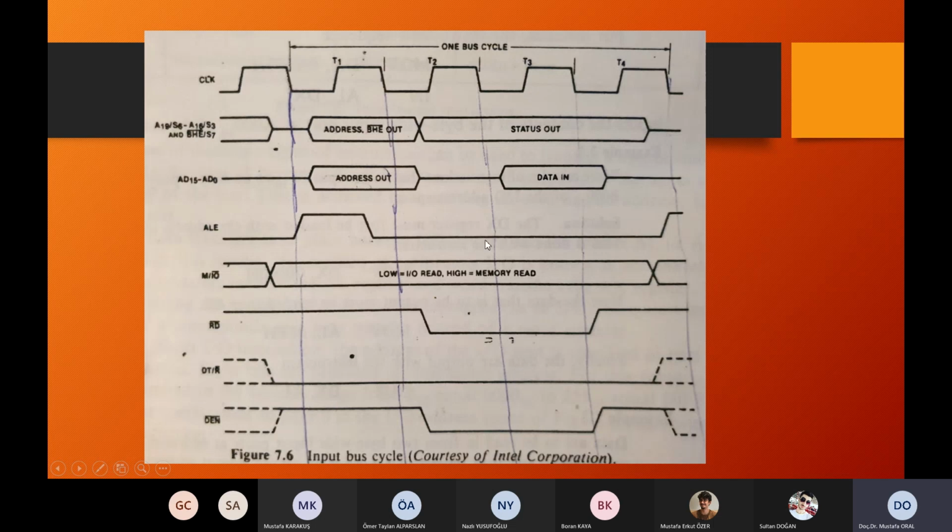If the microprocessor hasn't been presented address information and didn't latch it, it will not signal the outer device that the microprocessor is ready to read the information. That's why read and data enable signals are very similar to each other.